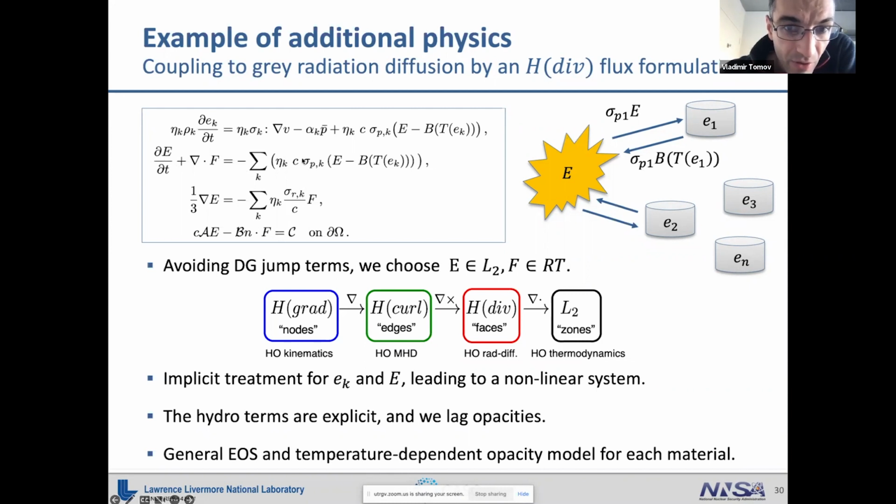It's a diffusion type equation because it's not transport, it's diffusion, and it's gray radiation. What they call gray means that we take only one frequency. This radiation is like light. It has many frequencies, and when you say, okay, I'm going to just do one frequency or 1 color, it's called gray.